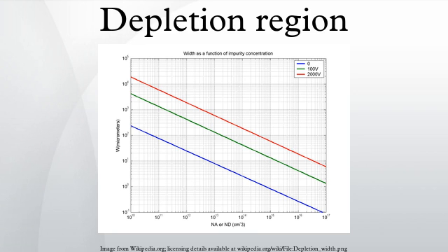1. Under reverse bias, the potential drop across the depletion region increases. This widens the depletion region, which increases the drift component of current and decreases the diffusion component. In this case the net current is leftward in the figure of the P-N junction. The carrier density then is small and only a very small reverse saturation current flows.